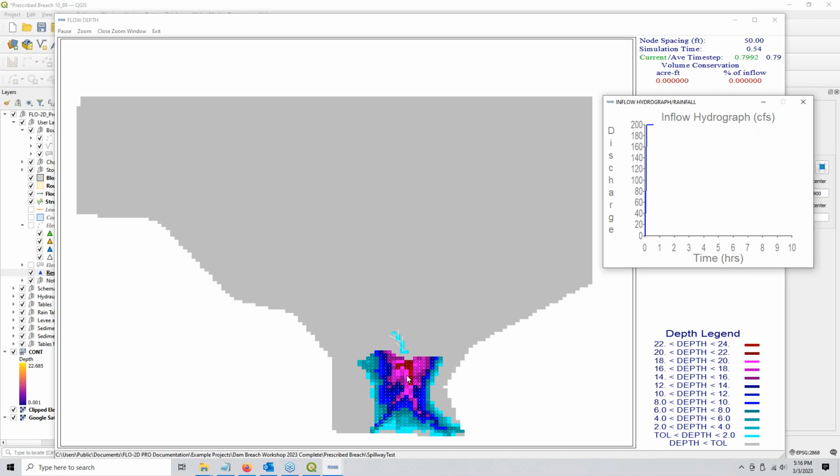And then I think you would probably need to run it a little bit longer than 2 hours to get that steady discharge of 200 cubic feet per second through the structure. Because I didn't get that, so probably I need to let it run longer than 2 hours because it's a bigger pond and it takes a while for that water to distribute and fill up to the correct elevation. We're going to let it run for 2 hours. We don't need to let it run any further because we see that it's working, and then we'll shut it down just to check the hydraulics through the structure.